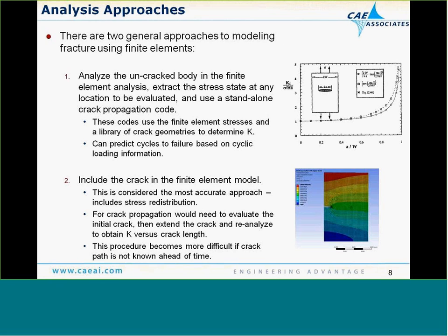Or the more difficult way is if you build the crack directly in your finite element model and then calculate the stress intensity factor. That's what we're going to talk about today, because that's some of the new features in Workbench. Keep in mind, it's a challenge to do this. There's a couple reasons. One is, if you're modeling a crack, the crack will affect how the load gets redistributed around that crack. So you won't get that effect using the first method. When you actually put the crack in your model, the load is automatically redistributed so that you get that effect.